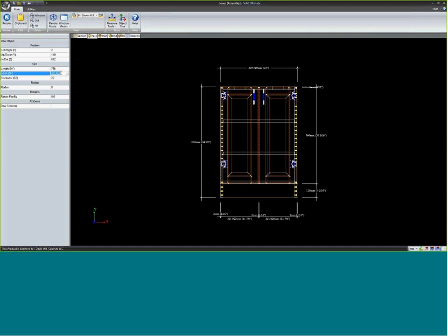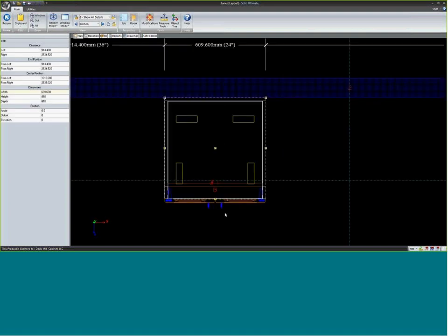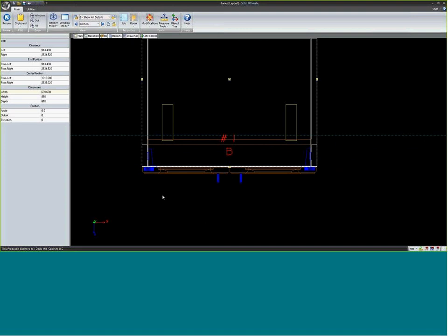Notice my width is a fractional millimeter. Our lists are going to round that up to 302. Nobody can read 301.8 on their tape measure, so we round that to 302. If it's 301.4, it's going to drop down to 301. The problem is that sometimes that can bite you. You might end up having some bigger gaps where you don't want them.